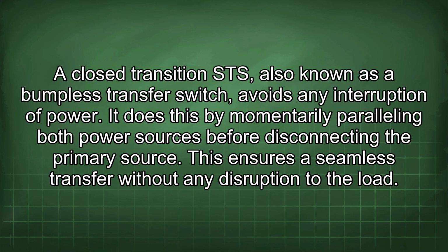A closed transition STS, also known as a bumpless transfer switch, avoids any interruption of power. It does this by momentarily paralleling both power sources before disconnecting the primary source. This ensures a seamless transfer without any disruption to the load.